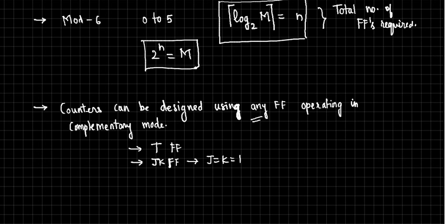How did we use a D flip-flop as a complementing flip-flop? How can we make use of a D flip-flop as a T flip-flop? Either by using an XOR gate, or we can simply connect the complementary output to the input. As simple as that.